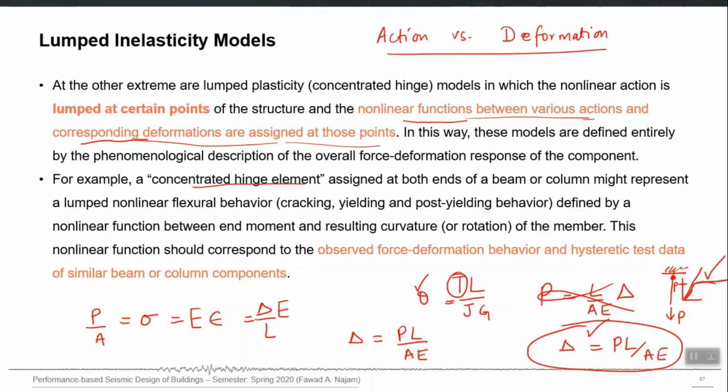Actually, I'll discuss that in more detail in the next few sessions. But in nonlinear modeling, this is the main question: from where will we first get the complete nonlinear force deformation curve of our action and deformation? There are several ways we can get these curves. One is from experiment, one is from analysis, where you perform nonlinear analysis at element level, develop that relationship, and give it in the computer model as an input.